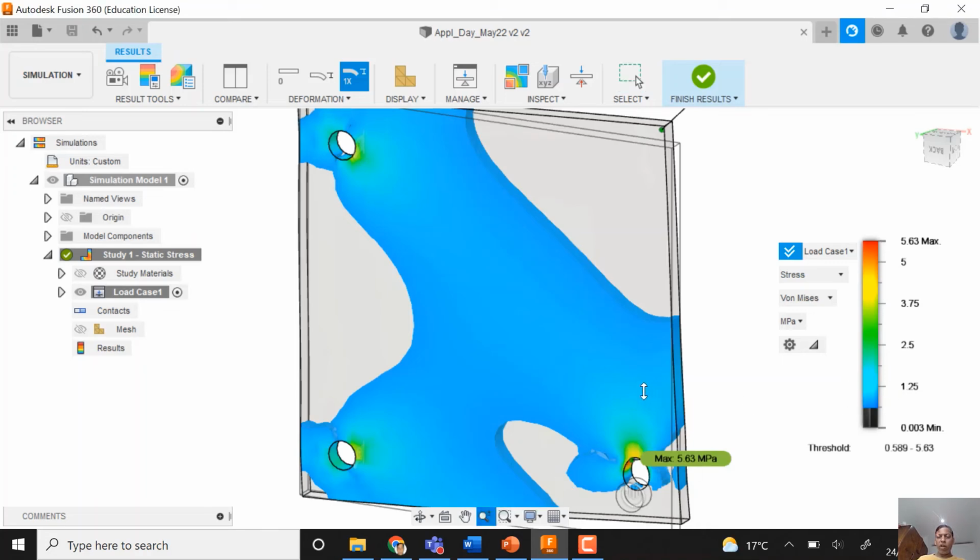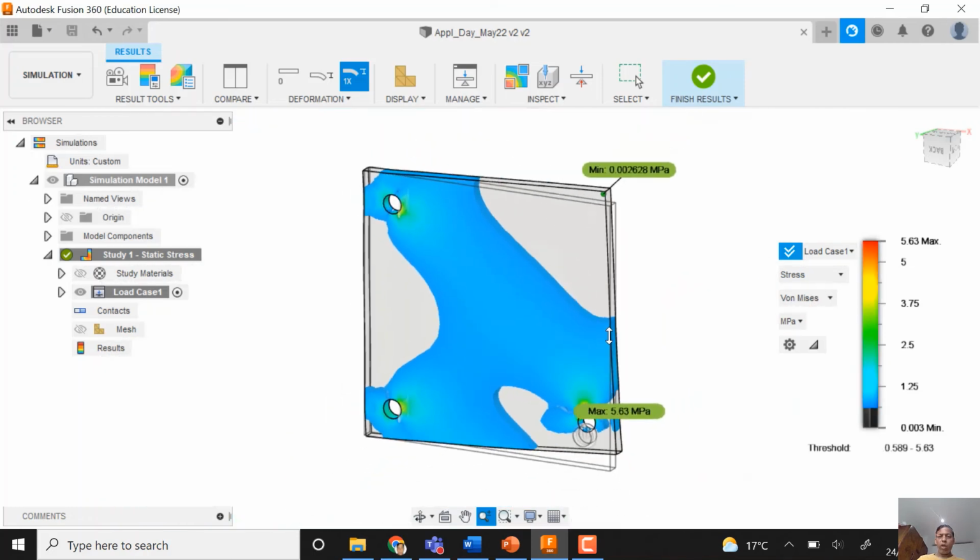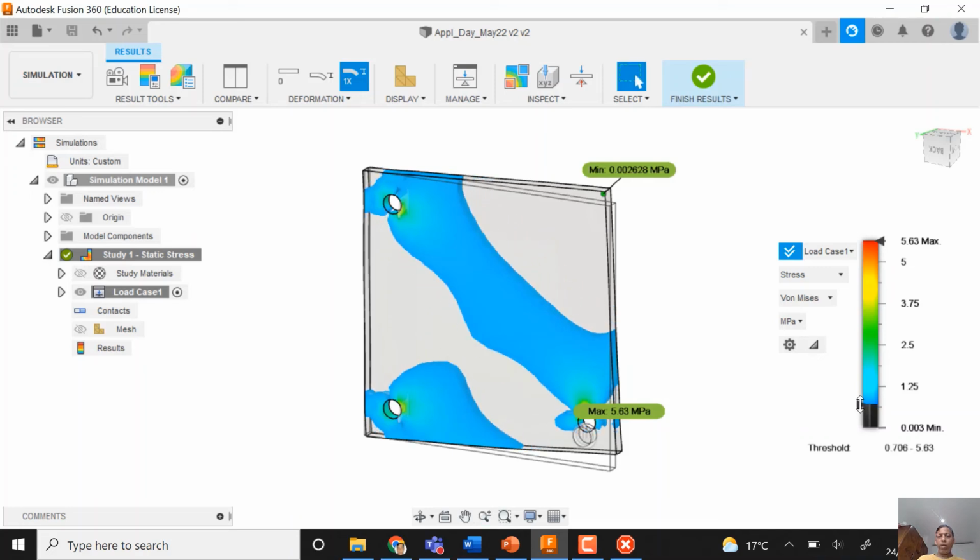Now the problem for this plate which I want to pose here is this: only the area which is right now colored is actually exposed to more stress, correct? So do we really require these other areas as a part of this plate, or can you just remove them and it can still bear the same pressure? Is it possible? If I want to make an optimum solution, or if I want to bear more stress, more capacity, what are the possible solutions?